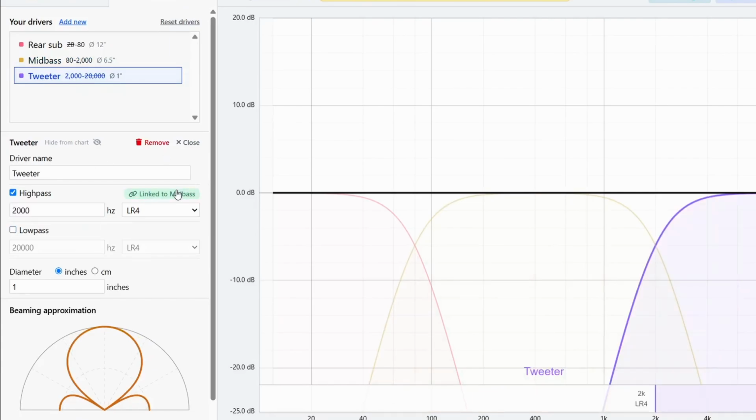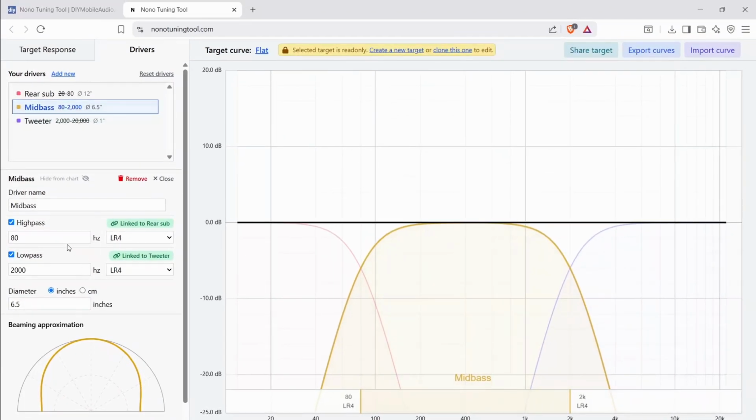We'll link it. So what you can see here is at 2000 hertz, the mid bass is starting to lose performance right around 30 degrees in. You would want to make sure that if you're using a 6.5-inch mid bass in your doors, say, if the angle exceeds 30 degrees relative to, say, your driver's ear versus your passenger ear, you would want to adjust the frequency response, if you can, for your crossover point for the tweeters.